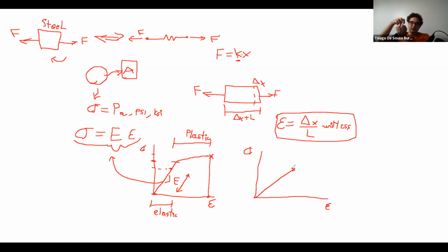In a metal, it's still able to take some more load. It won't come back to what it was before, but it can still keep going. It can still exist, and we can actually visually see it happening. In a composite, it will simply break out of nowhere. Pretty much no notice of it happening. So it's pretty scary.